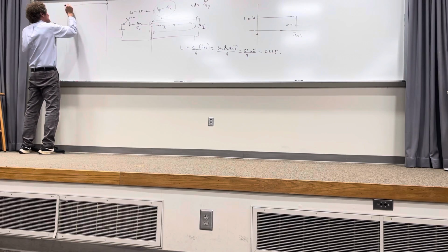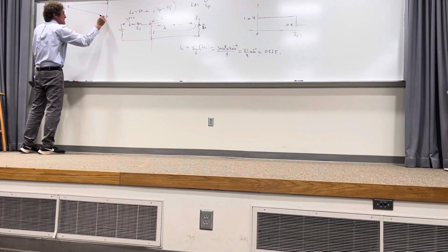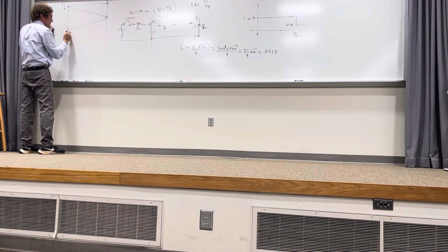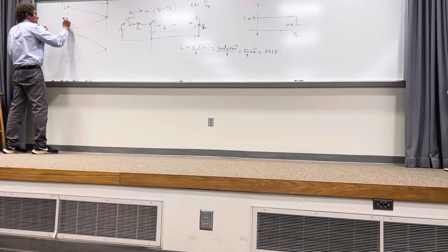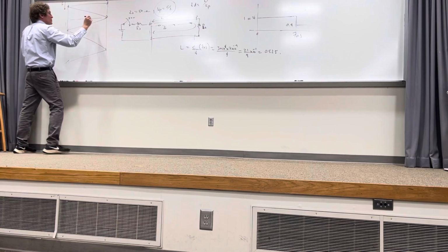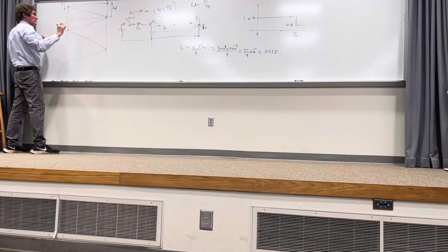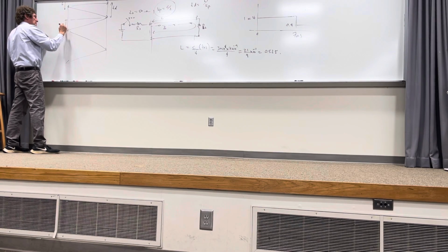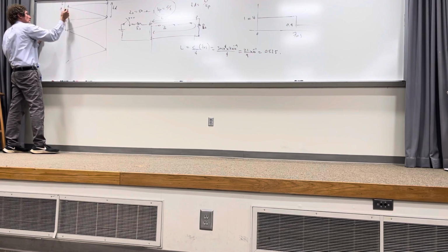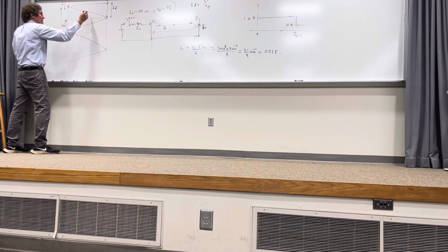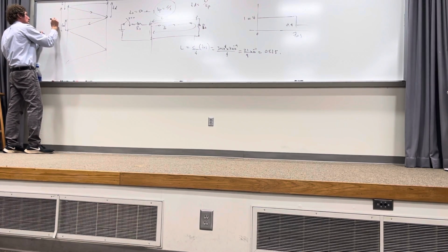Okay. So here's my version of a bounce diagram for this thing. This is L, this is 0. In this direction, it's time. And the bounce diagram looks like this. This, from here to here, would be just TD. That's the time it takes to get down the line one time. From here to here would be TD. The total time for the wave to hit the actual load and return would be 2 TD.